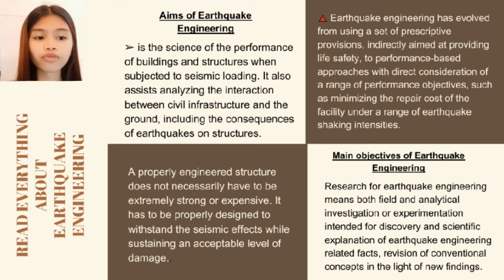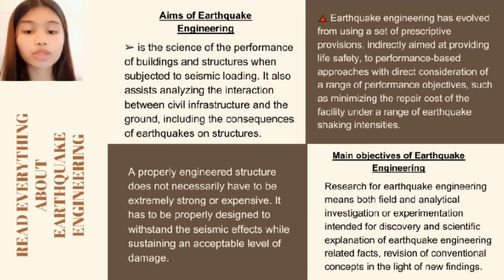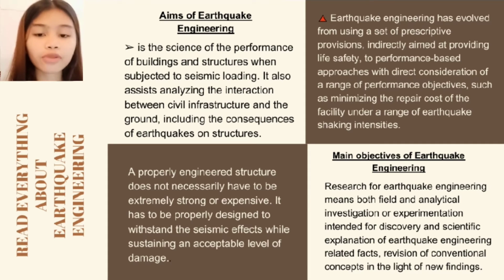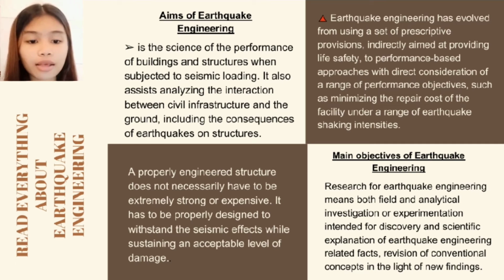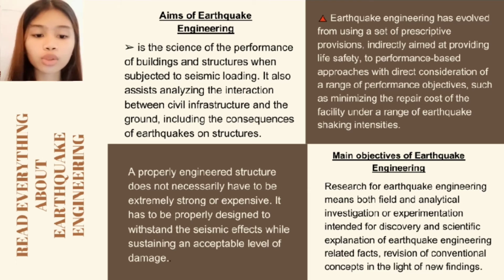Earthquake engineering has evolved from using a set of prescriptive provisions directly aimed at providing life safety to performance-based approaches with direct consideration of a range of performance objectives, such as minimizing the repair cost of the facility under a range of earthquake shaking intensities. A properly engineered structure does not necessarily have to be extremely strong or expensive. It has to be properly designed to withstand the seismic effects while sustaining an acceptable level of damage.